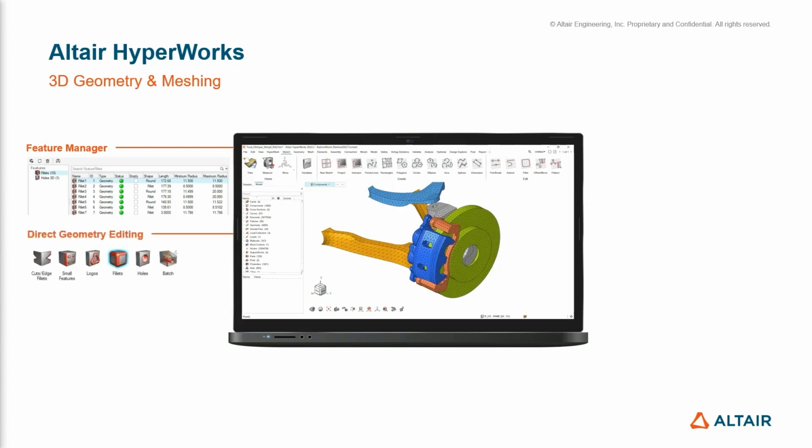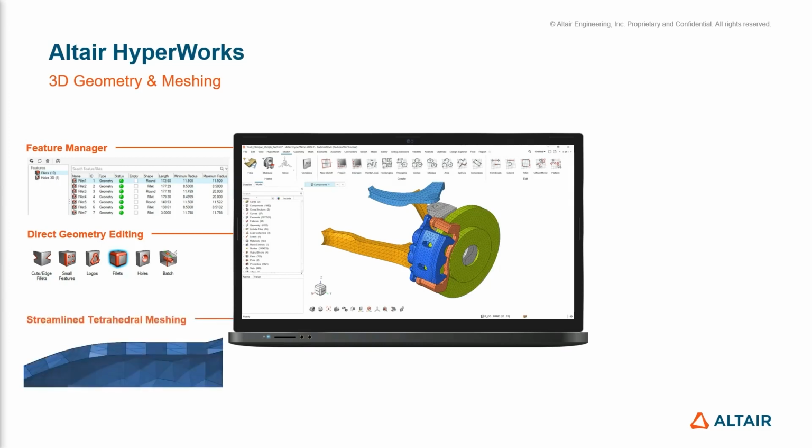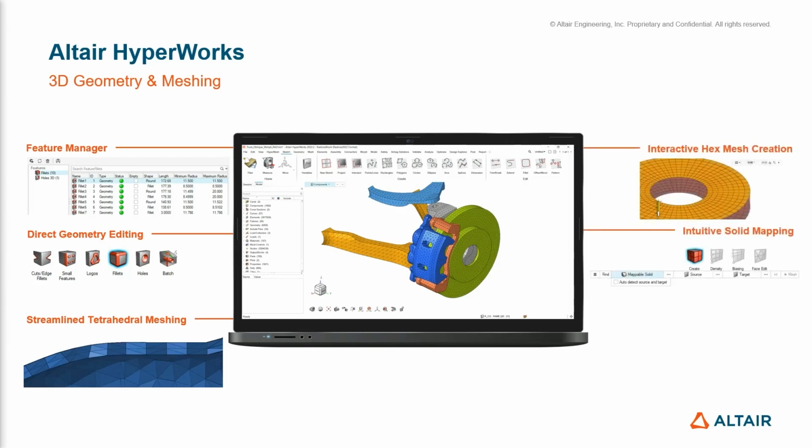We will then see how users can directly interact with their model to make changes, whether it be geometry creation, editing, or simplification. We will then go on to look at the meshing workflows, depending on the type of mesh we want to produce and that is appropriate for our application. In particular, streamlined tetrahedral meshing tools, interactive hex mesh creation, intuitive solid mapping, and quick extrusion of thin solids.